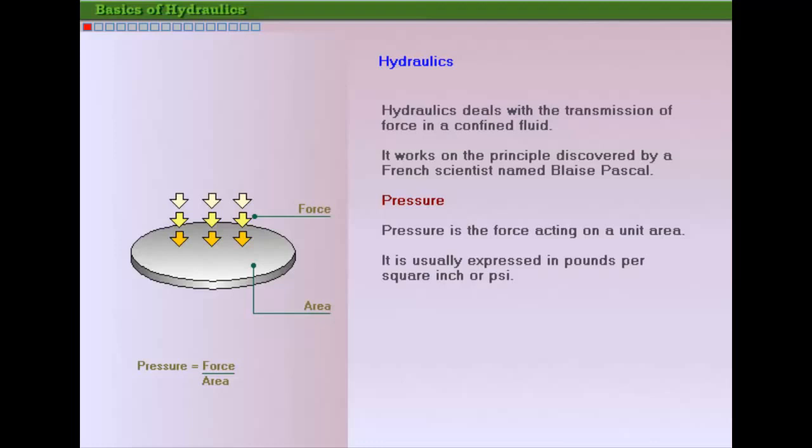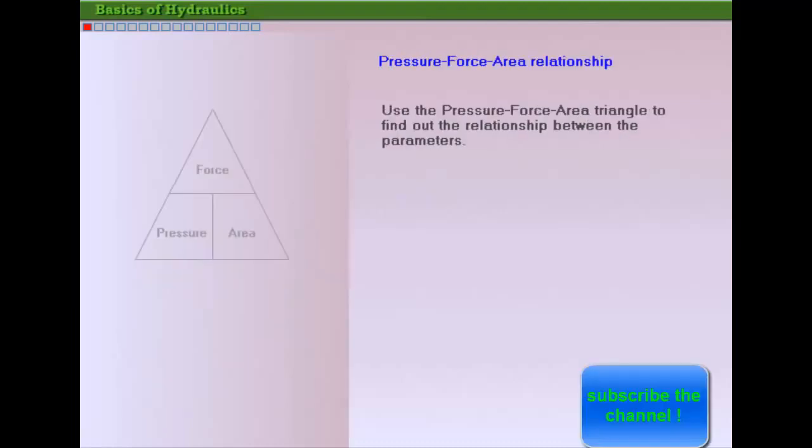Before studying Pascal's law, let's look at the relationship between pressure and force. Pressure is defined as the force acting on a unit area. It may be expressed in pounds per square inch or PSI. Let us work out the relationship between pressure, force, and area. This can be easily understood by using the pressure-force-area triangle shown in the figure.